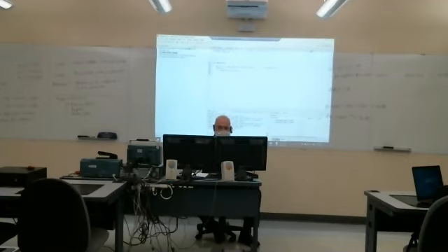And then now click on the little bug. Okay, looks like a tick to me, but click on that little bug and you'll go into debug mode. Now, it takes a while to make this transition. And actually, when it comes up, finally, it's still not here. Now I'm finally here. It's actually stopped, I think, at main. Okay. But if I click on the little green arrow to actually start running, you see the output here in the debugger console window.